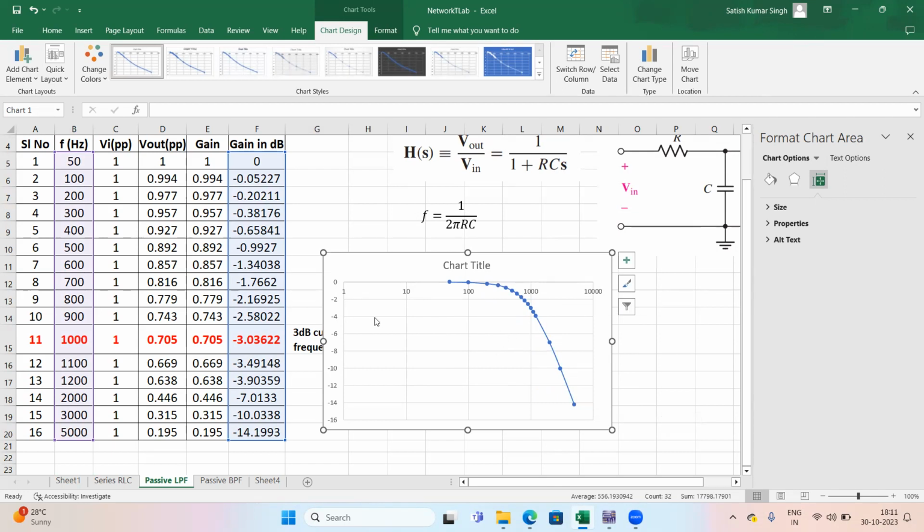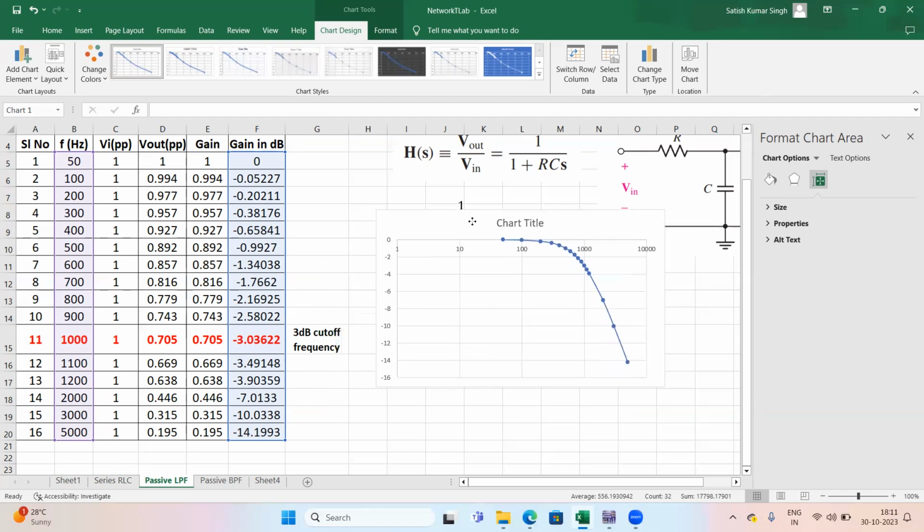So that's why it is normally called the semi-log paper, right? Here you can see in between these two lines, the frequencies covered are 1 to 10 hertz. But in between these two lines, it is 10 to 100 hertz. And between this line and this line, 100 hertz to 1 kilohertz. So you can see it is not a linear scale, it is a non-linear scale, and that's why it is called semi-log paper, right? So this way you can obtain your low pass frequency response.